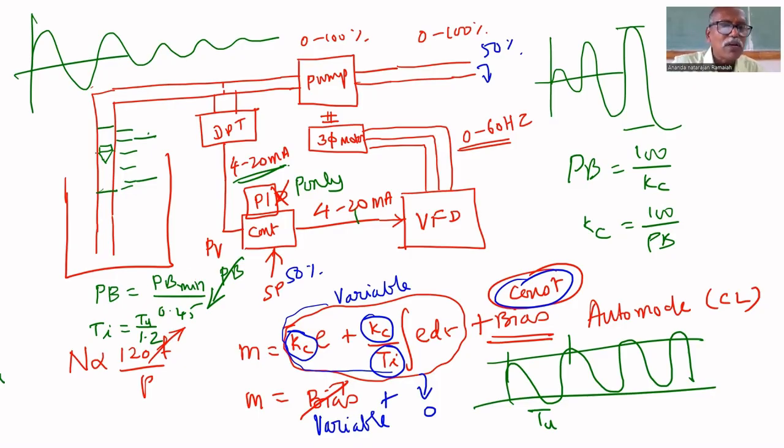Tu, how can it be found? It goes up and down. It means it exhibits sustained oscillation. So measure the time. A stop clock will be given. You can find the time. If you measure for one oscillation, there will be error.